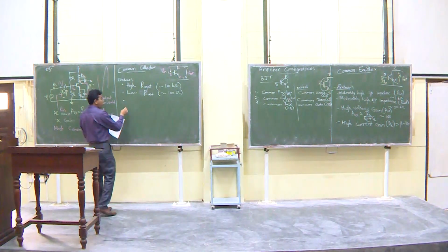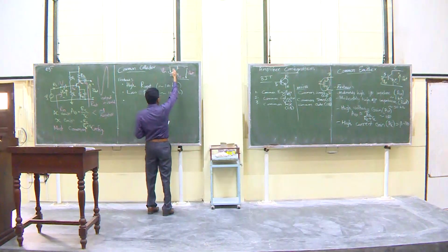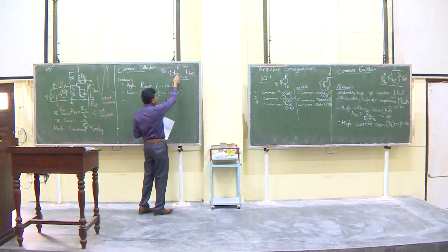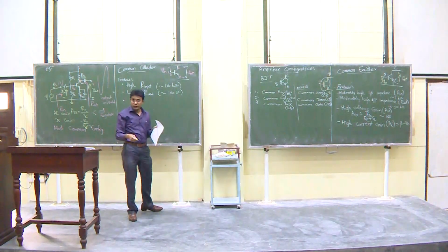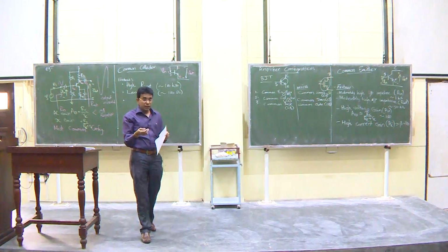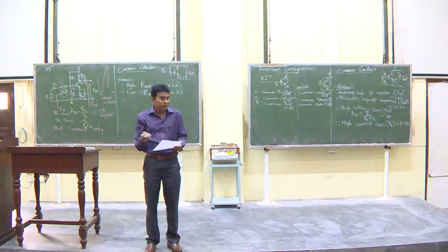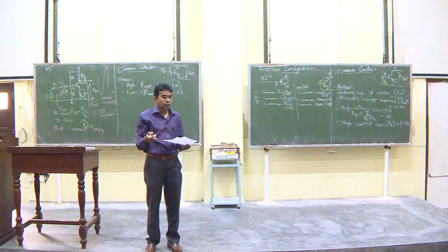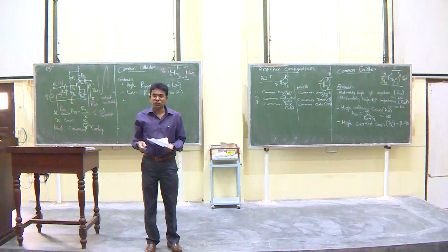And voltage gain, see that input is base, emitter is output. You know that there's a diode here which is forward biased. For DC voltages, there is a 0.7 voltage drop, but for AC voltages, there is basically very small voltage drop, right. So, therefore, input is pretty much the same as the output.